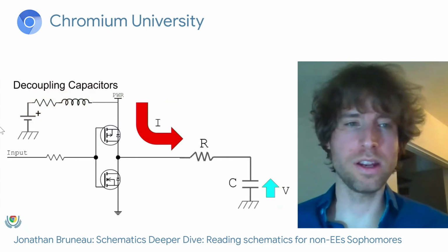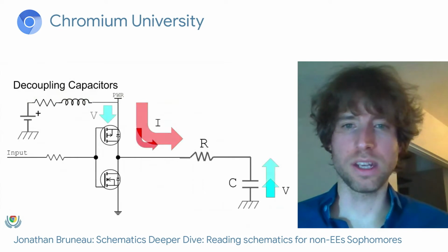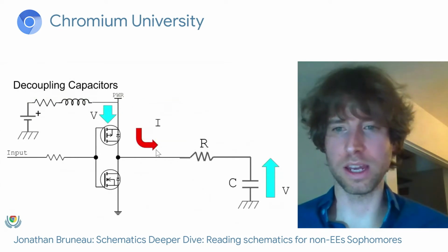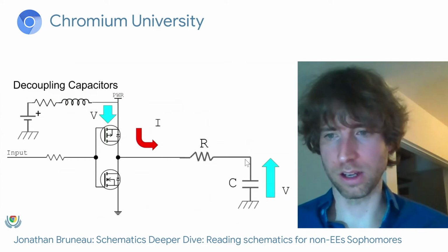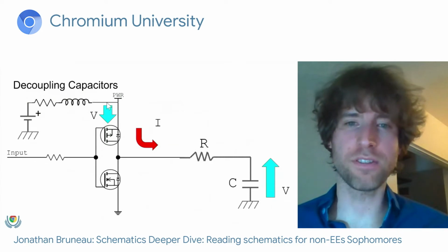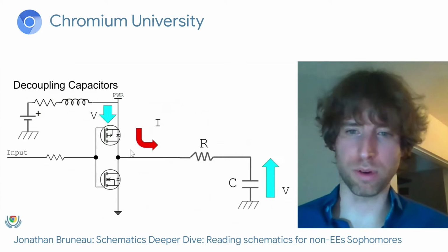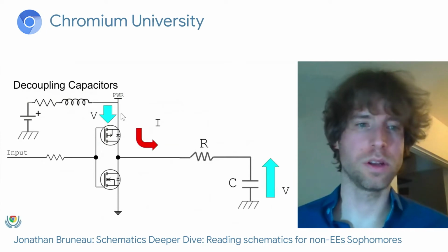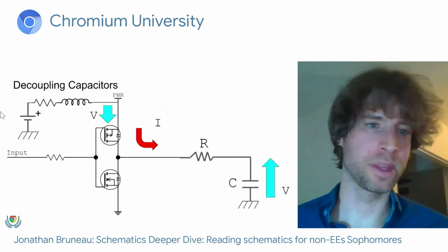So when you end up with a situation like this, as we have this large current coming in that needs to feed this RC circuit, there's not enough electrons here to properly fill this up at the speed that it wants to. And you'll end up with a voltage that starts to dip.